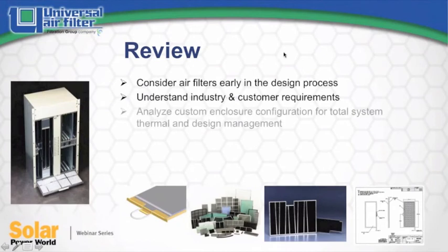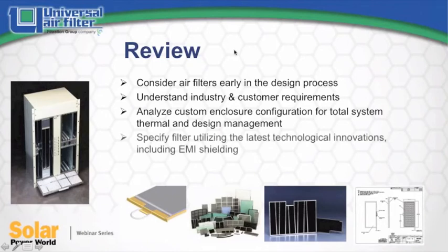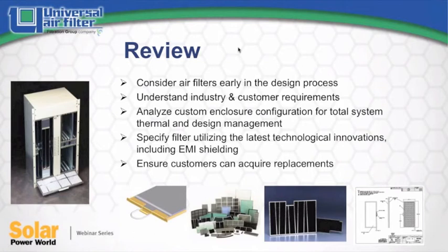Reviewing what we've gone over today, please consider air filters early in the design process. Understand your industry specs and your customer requirements, and analyze custom enclosure configuration for total system thermal and design management. Take advantage of the latest technological innovations and include EMI shielding capabilities if necessary. And always be sure that you, your organization, and your customers have access to OEM approved replacements.